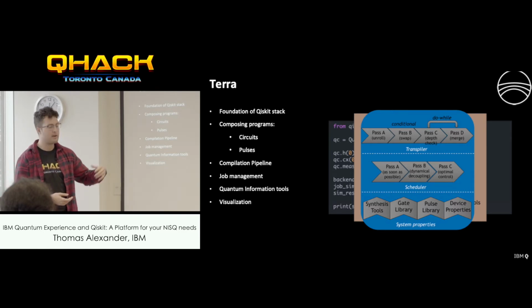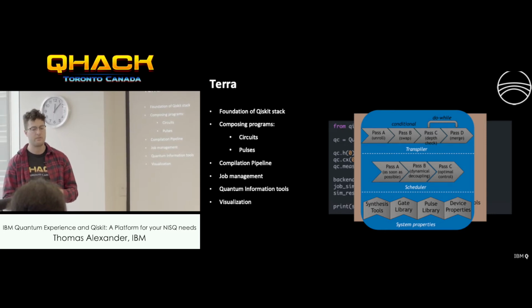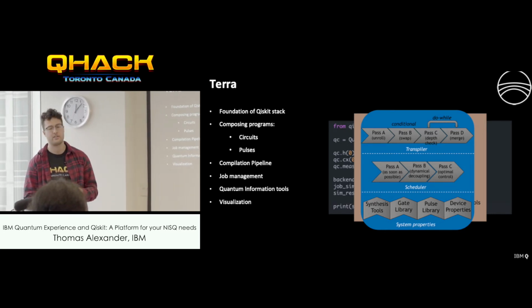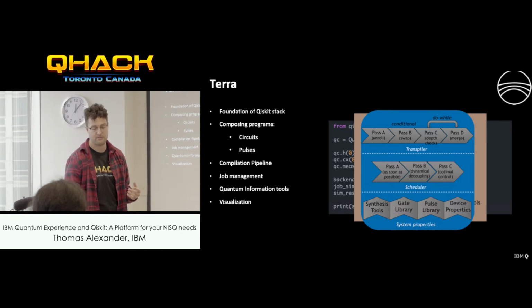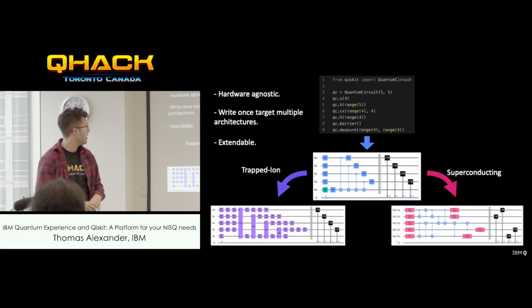And within Qiskit, there's a full compiler pipeline that's designed to be configurable, extensible, and open for research. So you're able to build your own series of passes to manipulate your quantum circuit and your pulse schedule. And then there's a lowering procedure that takes you to your pulse instructions. These operations are done in a way that they're cognizant of the underlying device properties, as these vary quite heavily from device to device in this near-term era. And like I said, it's a device-agnostic compilation framework.